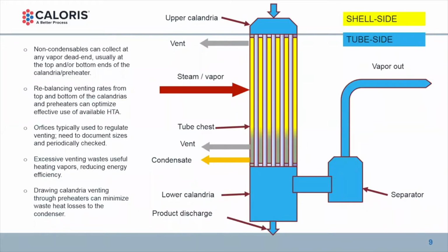Vacuum leaks introduce non-condensable gases into your system. In an evaporator that's operating under a partial vacuum condition, you want to utilize that available surface area. As I display here on the lower end of the calandria, this is trying to depict that we've gotten some non-condensable gases into this evaporator shell, and those gases are displacing steam from getting to the surface area. And I'm losing area. In my equation at the beginning, that A is getting smaller, and the only thing I can do is put more delta T in there to keep evaporating, which is just less energy efficient.